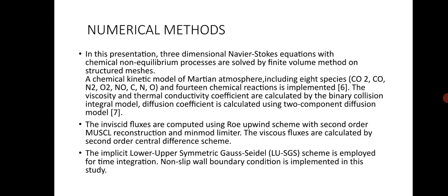The inviscid fluxes are computed using the Roe upwind scheme with second order MUSCL reconstruction and minmod limiter. The viscous fluxes are calculated by second order central difference scheme. The implicit lower-upper symmetric Gauss-Seidel scheme is employed for time integration. Non-slip wall boundary condition is implemented in this study.